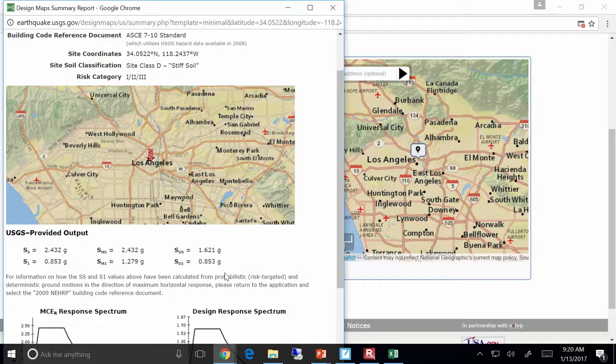Now let me restate that from a structural engineering aspect. When we design a building, we're actually selecting elements and saying the purpose of that element is to fail before the whole structure does. Makes sense? That's a weird thing to think about as a structural engineer, that you're selecting particular elements to fail, but it's exactly what you're doing. We call them structural fuses.